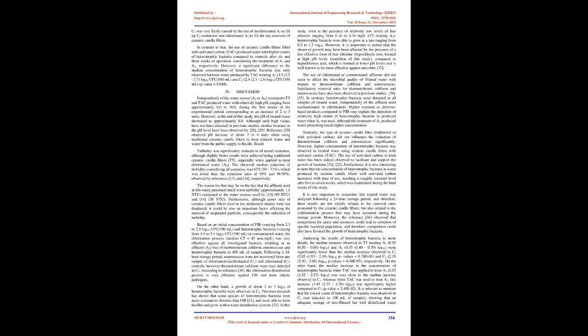D. The influence of usage time on pH and heterotrophic bacteria count in water treated by pot-type ceramic candle filters. Most of the investigated parameters did not present any correlation with usage time, with the exception of pH and heterotrophic bacteria counts, which presented strong correlations, considering the 10-week experimental period. The pH level of treated water, independently of the treatment applied, was observed to reduce more than 1 unit in this period, figure 4.